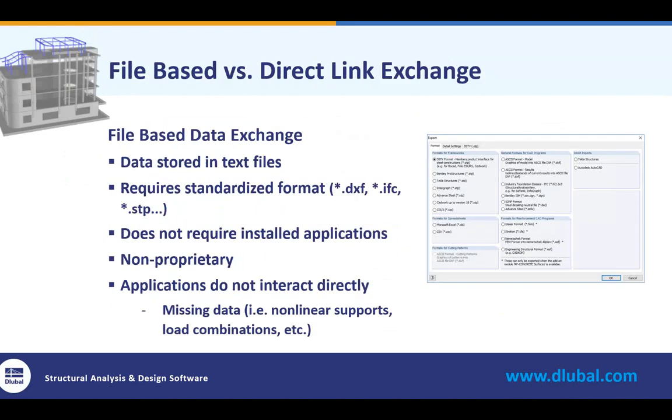So when we look at integration between two standalone programs, there's typically two different options, file-based versus direct link exchange. When we look at a file-based data exchange, this is where data is stored in text files. It requires a standardized format, and some examples for this might be DXF, IFC, STP, and other file extensions. So within RFEM, you can see here for the export and import options, we have all of these different data exchange file extensions available. You'll see here STP, DXF, DAT files, and so on.